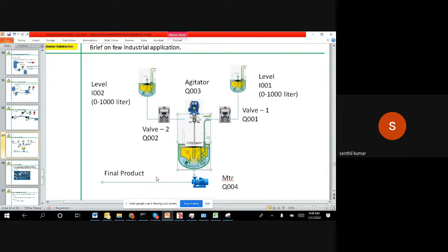Those will always be used, but the calculation also takes some part, because without AND gate, OR gate, set result, flip flop, timer, counter, you cannot do a logic. It's very hard to achieve any logic. Those are very basic. As I told you, they cover 70 to 80% of the complete logic implementation in any PLC.